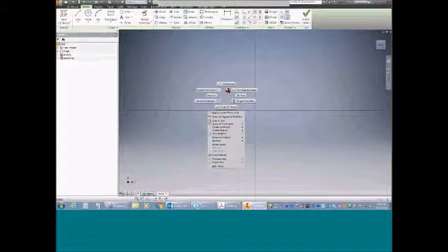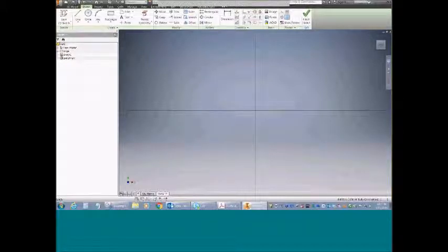So there are lots of different ways I could approach this, and I ask them to approach it a very specific way because I'm trying to really get them used to sketching individual pieces of geometry and getting used to the constraints. One way that we could accomplish this task in Inventor is to simply put a rectangle in here and then latch a circle. I'll just latch it onto the midpoint there. And that would be a perfectly acceptable sketch for that part.